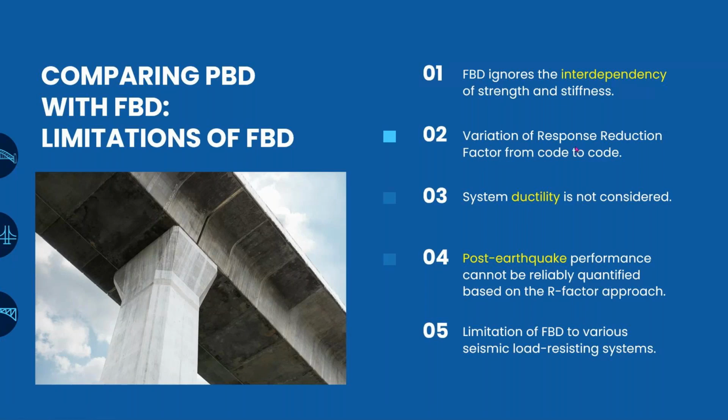Which is not true under one particular seismic event. So that is ignored. The system ductility is not considered at all. Then we do not know what the post-earthquake performance of the structure is, and as there is no reliable quantification of the R value, we could not predict what the structural status would be.